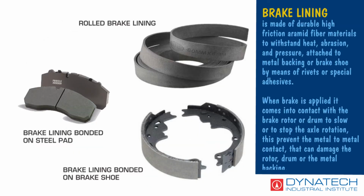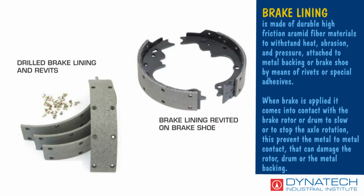Brake lining is made of durable high-friction aramid fiber materials to withstand heat, abrasion, and pressure, attached to the metal backing or brake shoe by means of rivets or special adhesive. When the brake is applied, it comes into contact with the brake rotor or drum to slow or stop the axle rotation. This prevents metal-to-metal contact that can damage the rotor or drum and the metal backing.